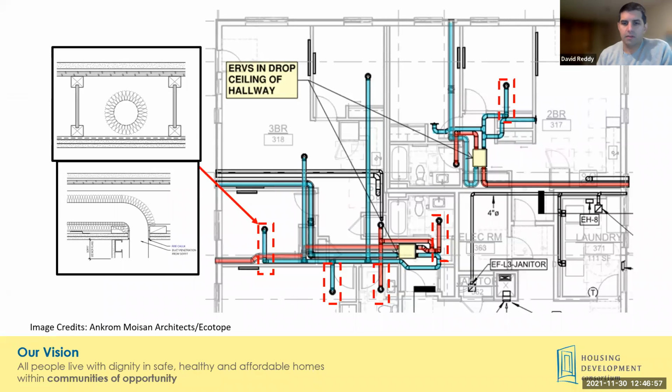One thing that I also wanted to highlight is one of the challenges you'll find when locating all these ducts within the dwelling unit. Soffiting or dropping ceilings is our recommended first approach because that avoids penetrating the rated membranes of the floor assembly.